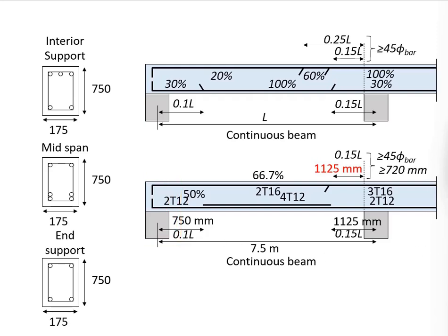In this case, it is not the more reinforcement bar, the better. When it is heavily reinforced at one place, congested, you might have an issue with bonding with concrete due to poor quality of bond here.